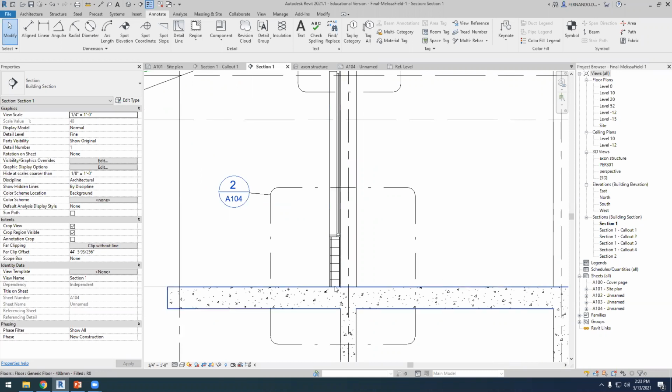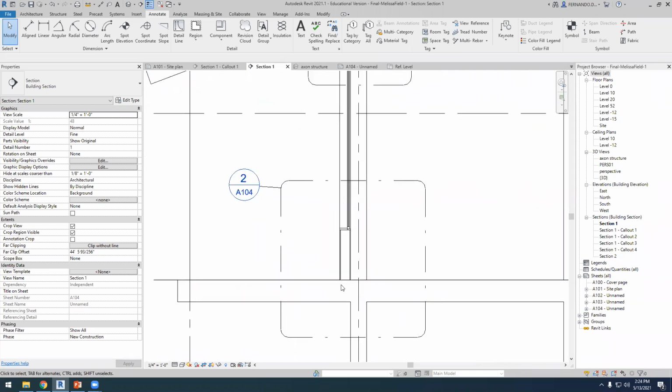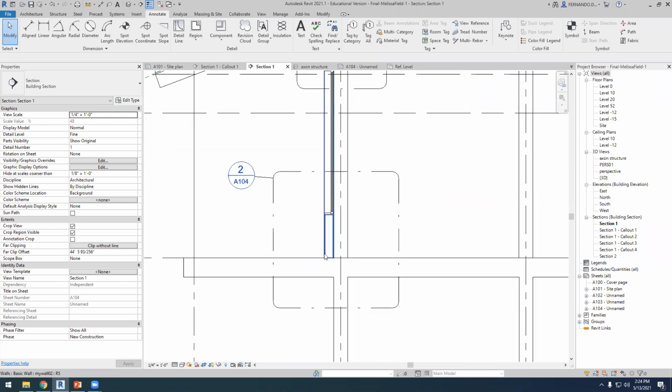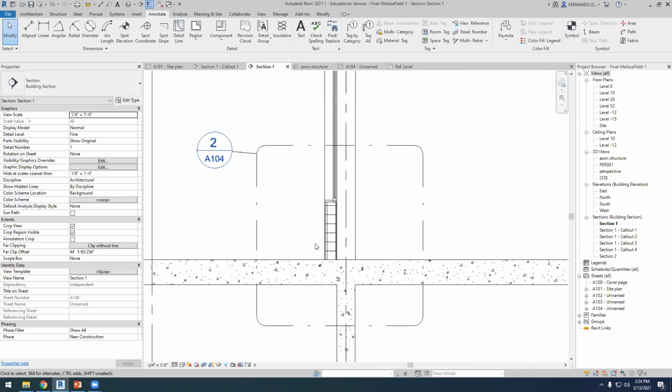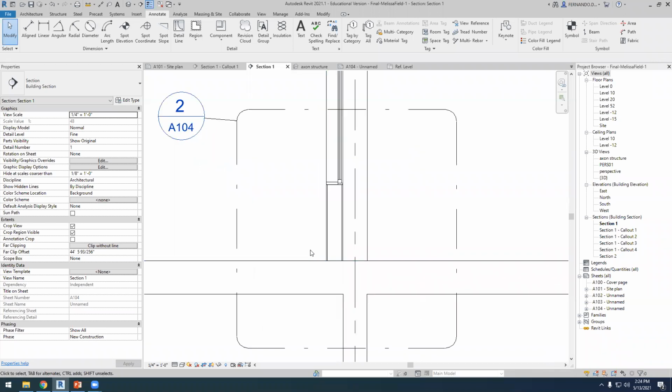We have to get rid of it. So we have to move the water out. So we need a slope. And again, at that scale, maybe we won't notice that there's a slope here, but when we're working with the callout, we need to convey the idea that this is sloping out of the building. And not only do we need a slope going out, but we need something here to collect the water that might be hitting the glass.